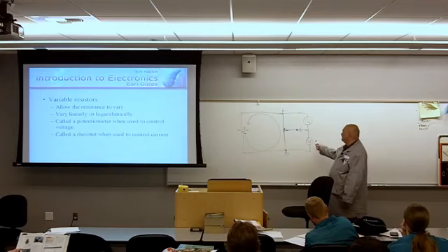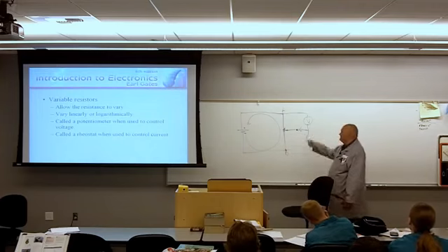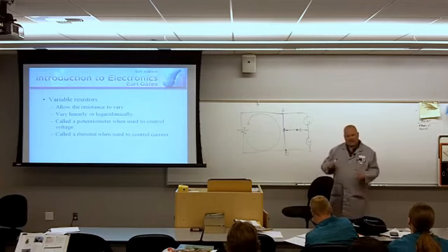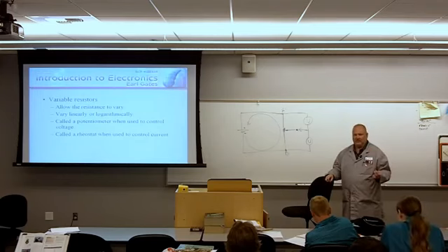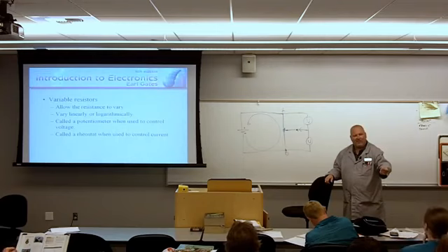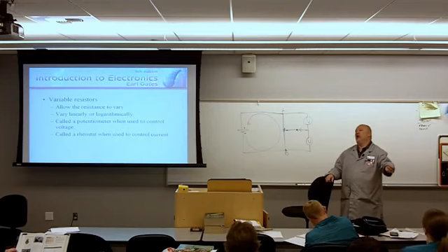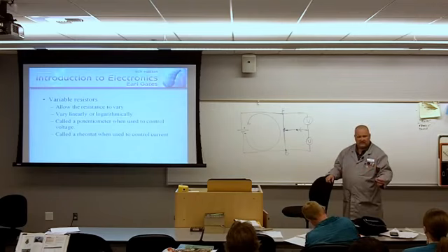potentiometer. This is how the volume control on your stereo is connected. That voltage that you're controlling is going typically to a transistor, and it's telling that transistor, here's more voltage, I want you to amplify more and make the music louder, or turn it down and make the music softer. I'm going to give you less voltage to the amplifier, the transistor. And this is how it works. So keep that in mind.